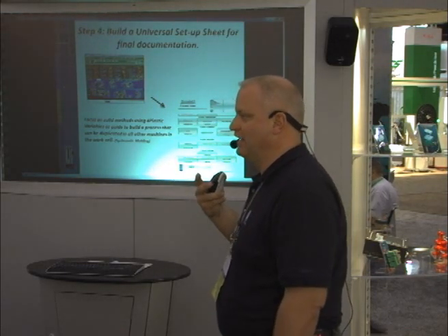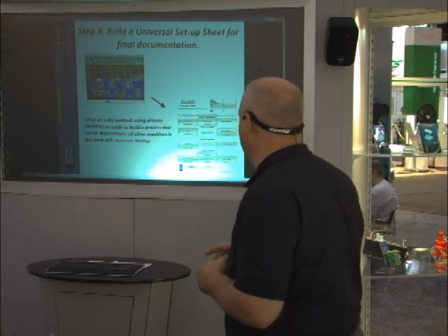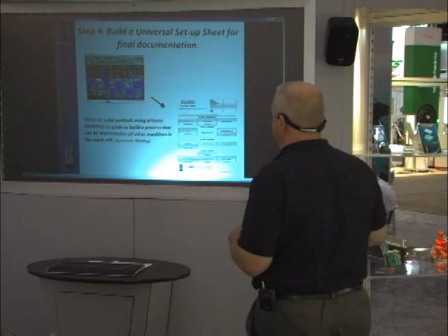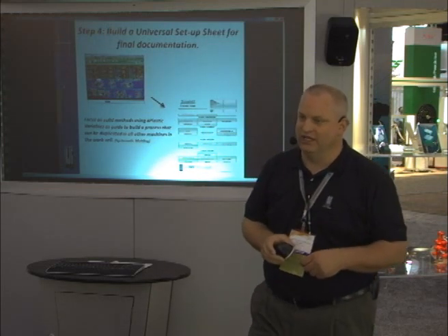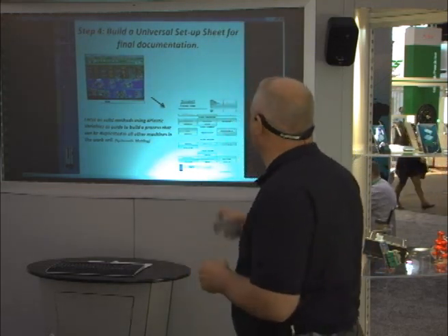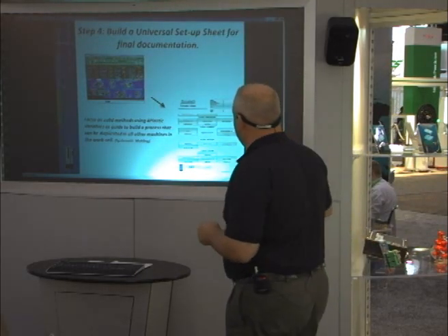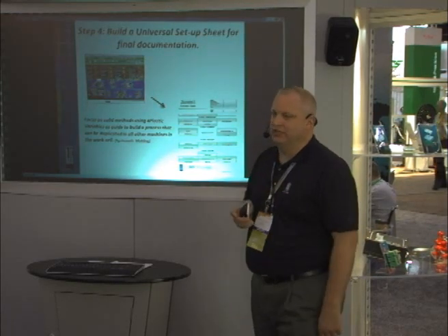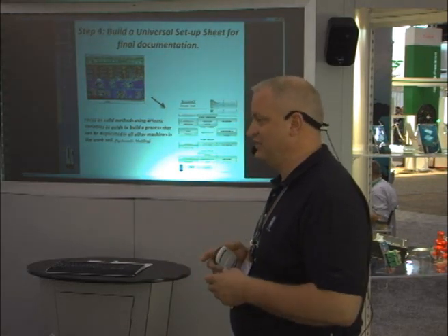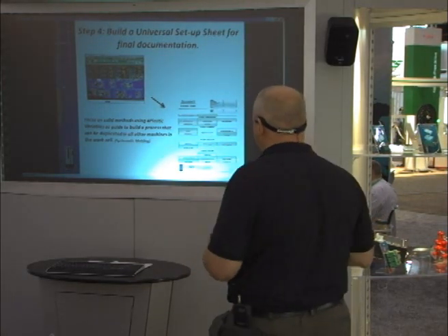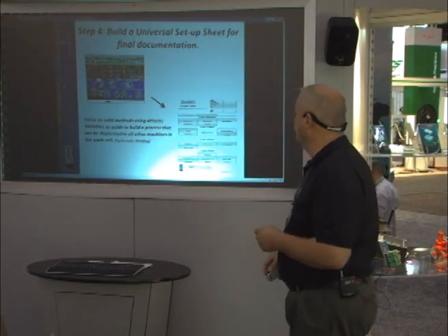I found the areas where I had deficiencies in my simulation data and found out that that was really somewhat machine related, and also some cavity pressures, and now I've finalized that, and I can actually come back and build a nice solid decoupled tube process sheet utilizing a universal setup. Once I have that universal setup, I can take this information and I can duplicate it in my other machines because I understand what their screw sizes are, I understand what the clamp size is, I have all the variables I need to match up with this, okay? So really systematic molding approaches.